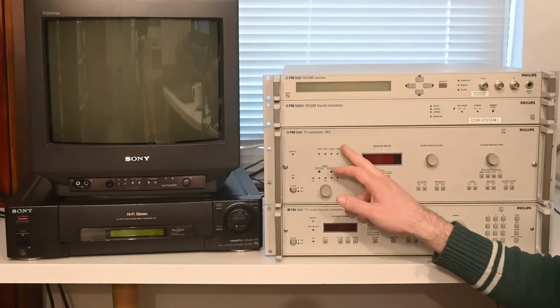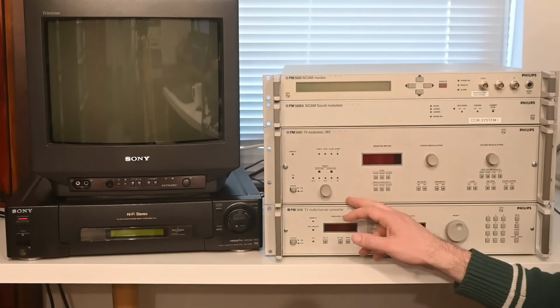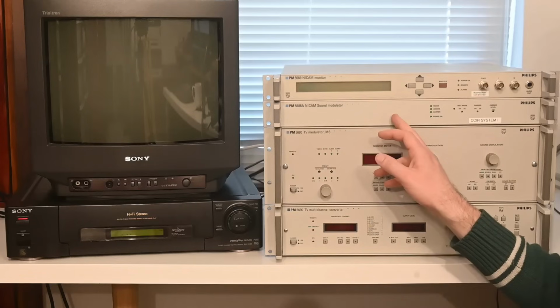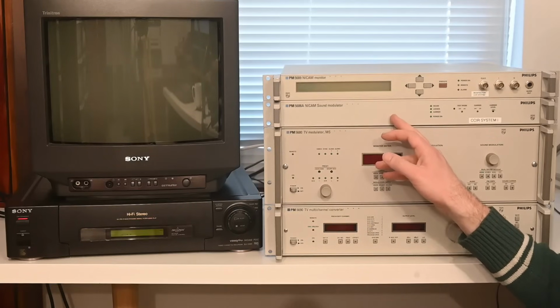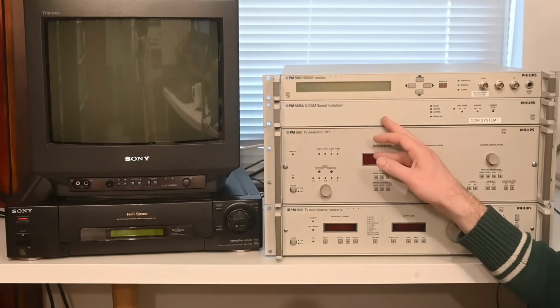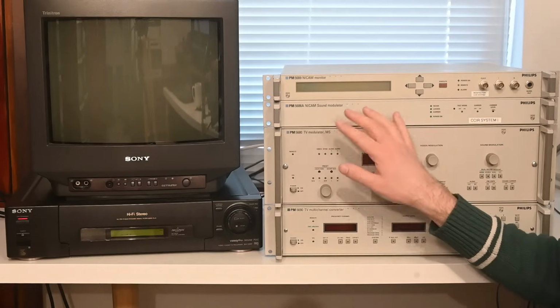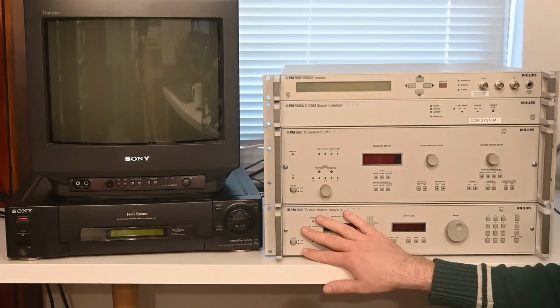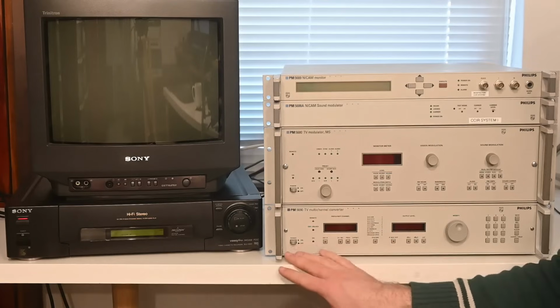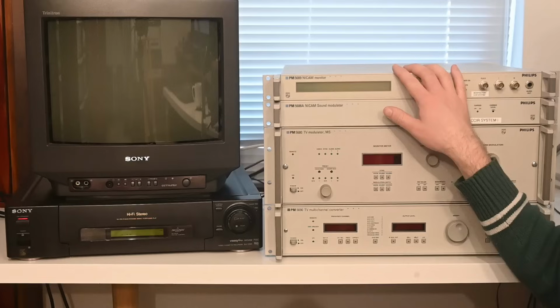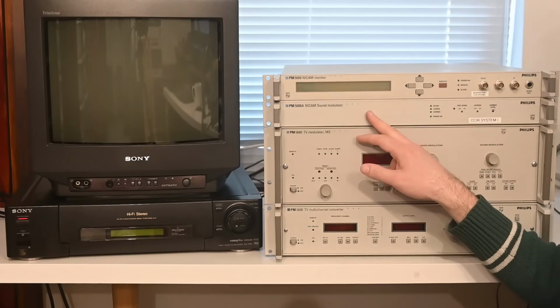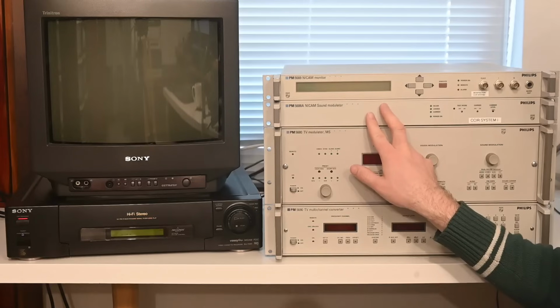So the vision signal is going into this vision modulator, and the NICAM digital audio signal goes into this NICAM modulator. This is a pretty dumb item, so digital in and digital QPSK carrier coming out, really not much going on in there at all. The outputs of these two are combined into this up converter unit, and from there it heads on to the receiver. I also have this monitor, and that's connected to the modulator. This is just here for demonstration purposes. We'll talk a bit about what that's going to be demonstrating when we switch all of this on.